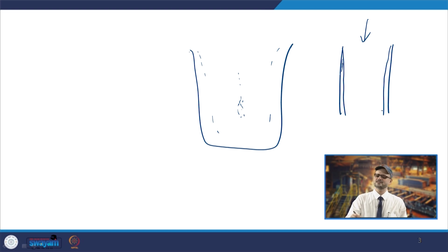Now, this solidified layer has to leave, it has to come continuously downwards, otherwise the layer will be fixed and it cannot go further. So, you had to do something so that it comes down and leaves the mold. For that the oscillation system was there, and also another mechanism, something between these two interfaces, so that it does not get stuck.